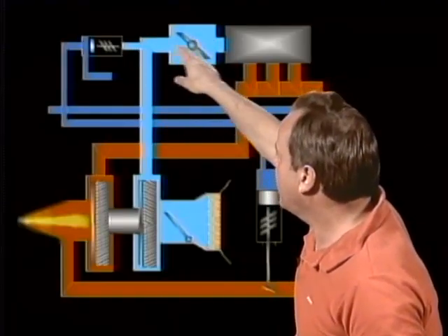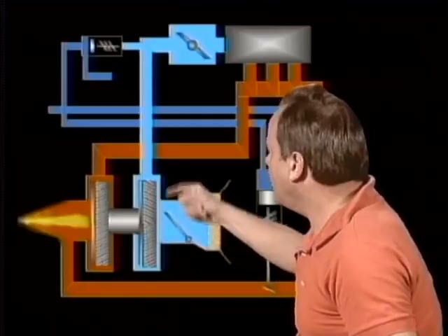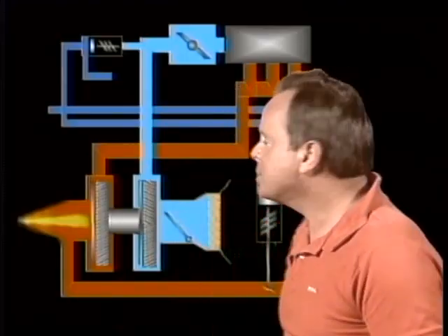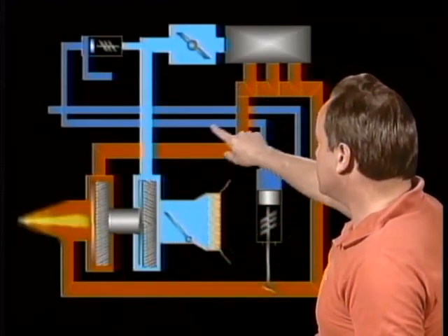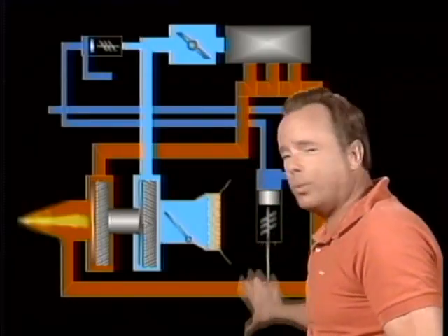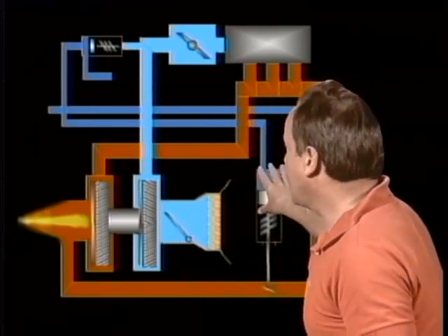So we're going to have 29 inches of manifold pressure before you get to the throttle valve all the time, and we're going to run this compressor hard enough to always maintain, we'll say, 29 inches manifold pressure. That's called the absolute pressure controller, and it does the same thing. It either bleeds or does not bleed oil pressure off the wastegate actuator there.